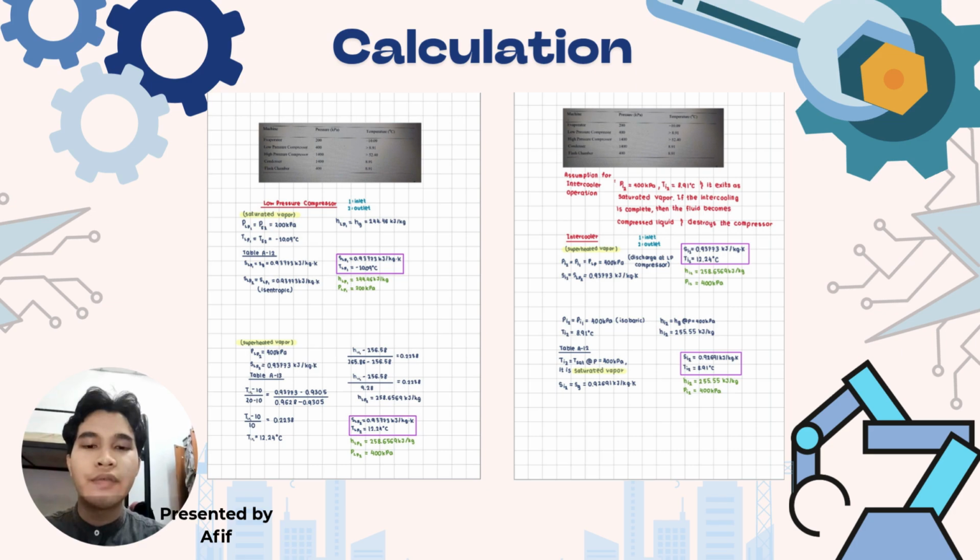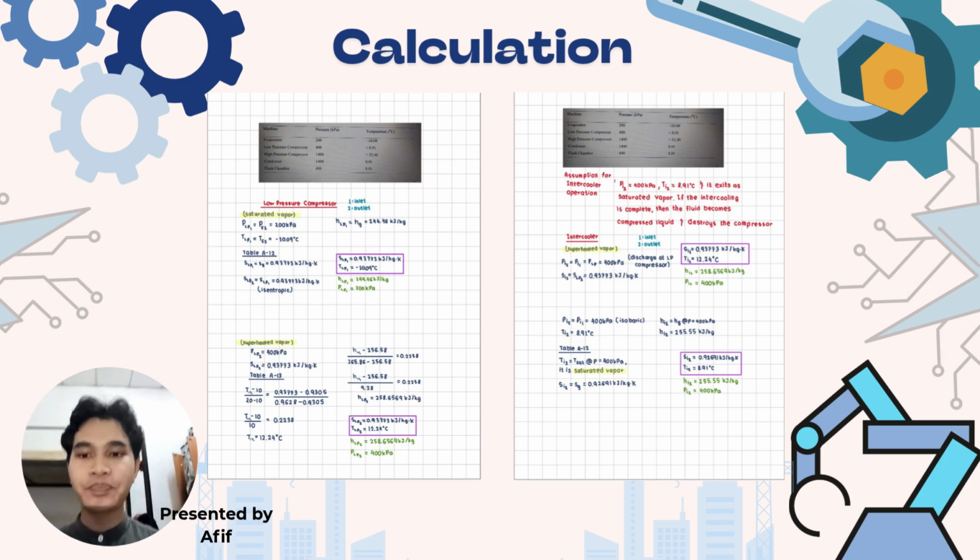Now we're moving on to the full in-depth calculation for the TS and PH diagrams together. There are several components that we have integrated into our advanced refrigeration system, which are the multi-stage compressor, which is the low pressure compressor and high pressure compressor, an intercooler between them, the condenser and subcooler, followed by the expansion valve, flash chamber, and second expansion valve, and then finally connected to the evaporator part.